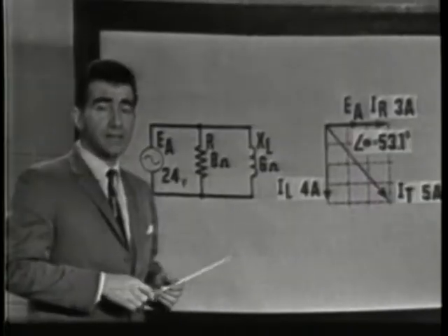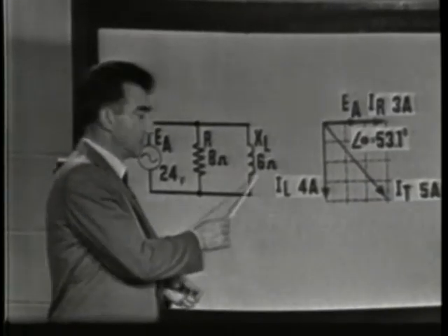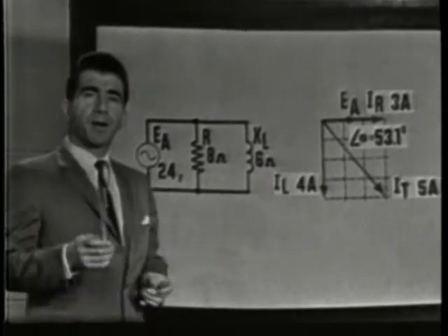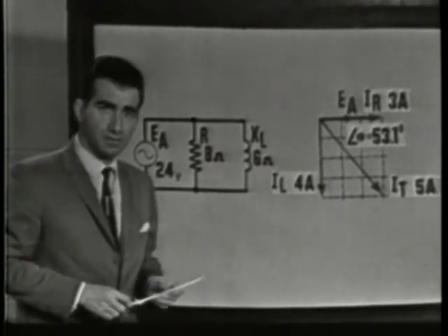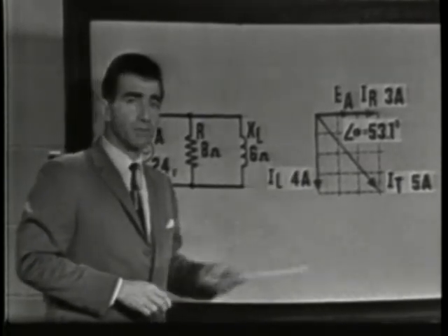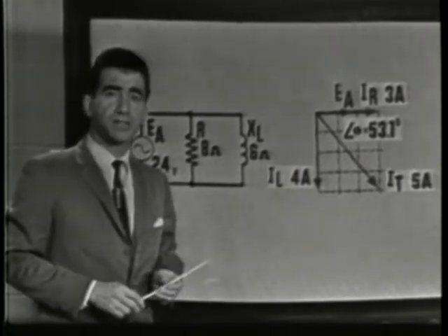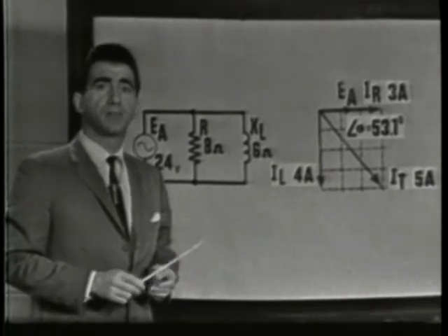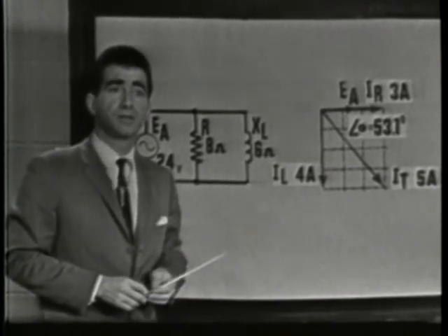Which you will note is less than the smallest impedance in the circuit. Now, perhaps one of the most important characteristics of a reactive circuit is the phase angle, which is determined by the ratio of resistance to reactance, and may be determined very simply by using trig functions, which, as you know, are determined by the amounts of resistive and reactive currents in the circuit.